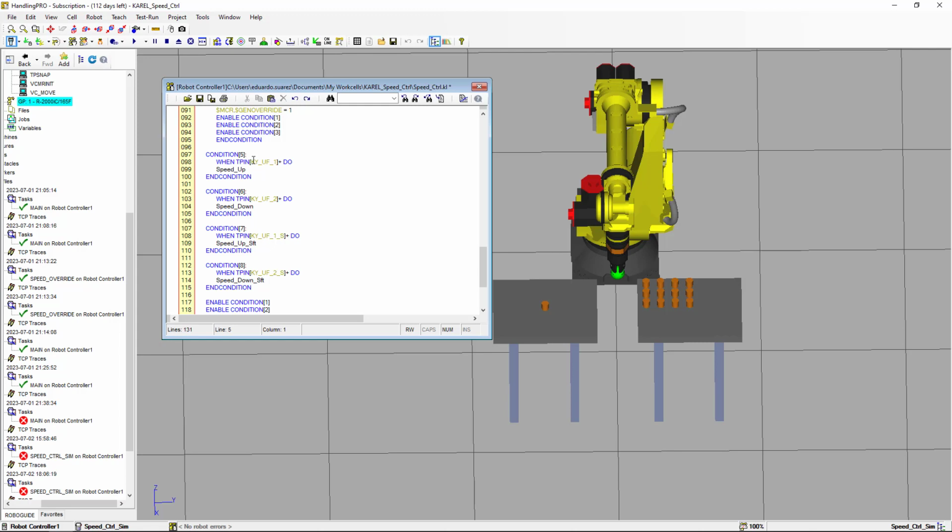The instruction that we're going to use is port ID EP in, and in brackets we add the code number for the user tool 1 key, that in this case we're going to replace with the variable name that was defined in the file that was included in the translator directive. So it has a more meaningful name than just the code number for the teach pendant key.